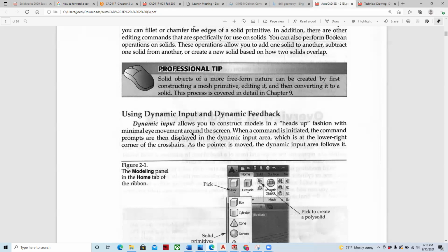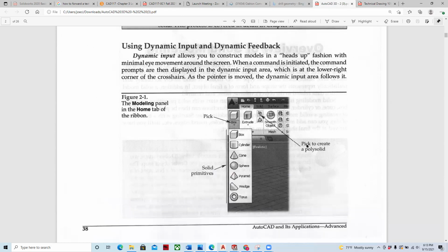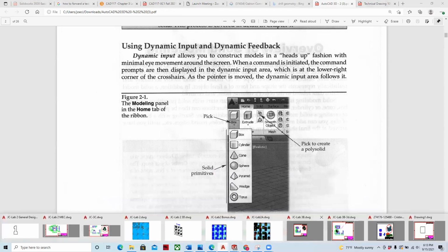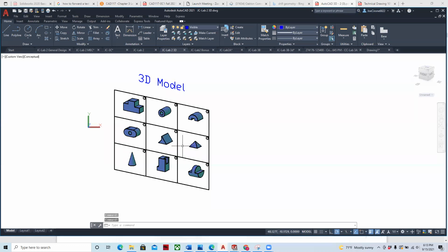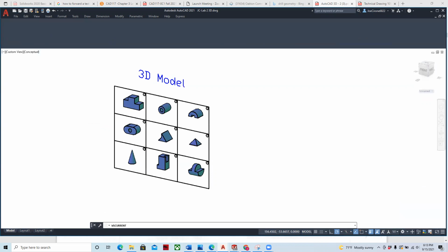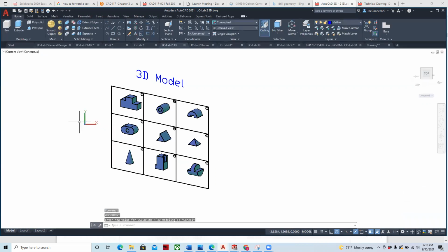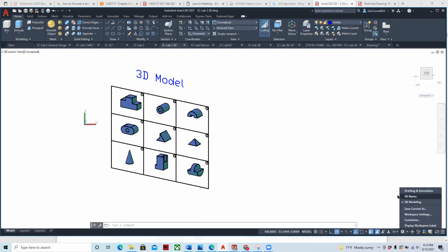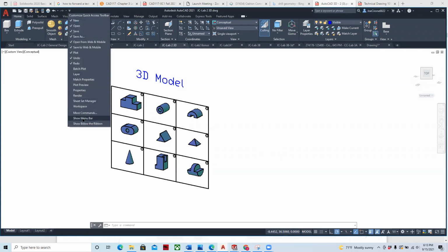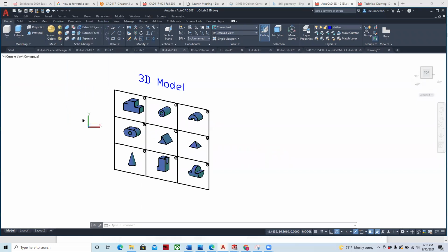We can work with a 3D interface or a 3D workspace by going into our CAD system. And let's pull up one of our 3D drawings. And then switching over our workspace to 3D modeling. How do you do that again, Joe? You hit this gear right here. Yes. And then you enable 3D modeling. And left click on that? That's correct. And I also like to turn on the menu bar. It sort of resets it. So I'll reset the menu bar as well.